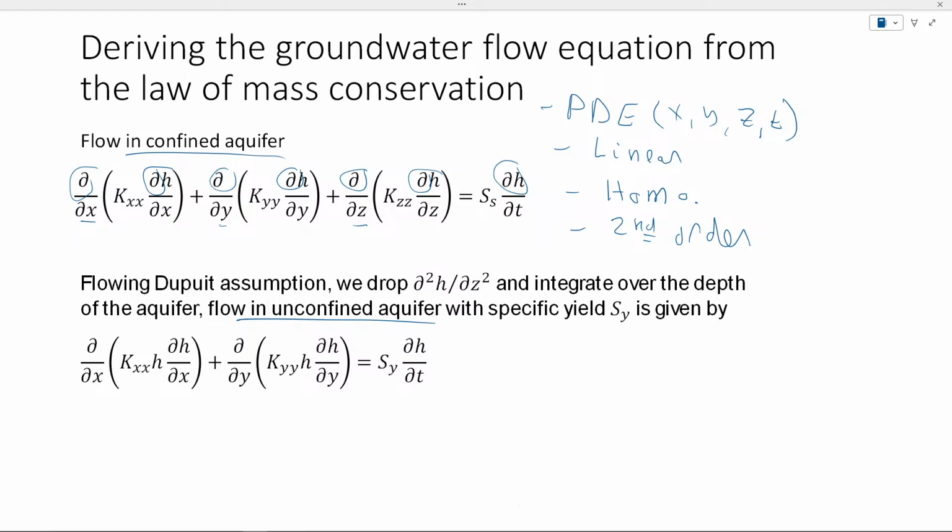For the unconfined aquifer, we can have the Dupuit assumption, basically that head is not changing vertically, so head is constant along the z direction. So this is the z direction. The head is not changing vertically, it's constant, and we just have this horizontal flow, so we can get rid of this term. And in this one here, the head is a function of its derivative. So here we got this head, like you see here, versus here. Here head is a function of its derivative.